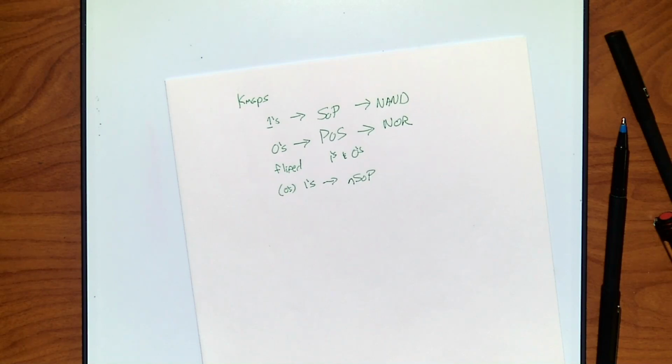So I could handle the zeros in essence using sum of products. Because sometimes there's only a few zeros, and so encircling them's really easy. And to get the ones, it would be some crazy collection of them with 20 encirclements or something stupid on a big design. So sometimes we just want to avoid that, but we still want to stick with encircling ones. So we flip them.